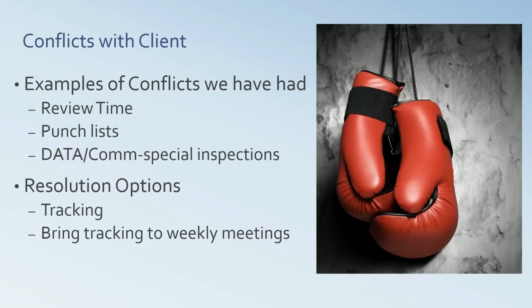But regardless of that, if you're coming in and the client is punching finishes, that's not the same kind of punch list as a mechanical punch list or an electrical punch list or telecom or any of these other specialty systems. So that's the only caveat to this. If you've got people coming in for the client that's looking at lipstick and rouge, and then you've got another team that comes in and they're looking at the mechanical, that's just going to happen. Absolutely. And then you've got to merge those punch lists together, but you don't want this group coming in on this day to look at this, and this group coming in on another day to look at the exact same thing. You want to get everybody there.